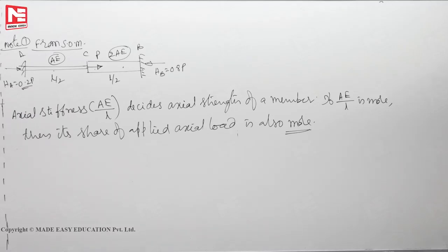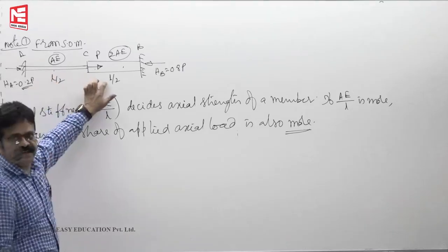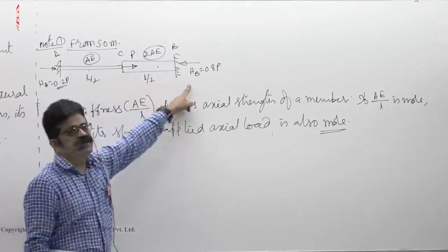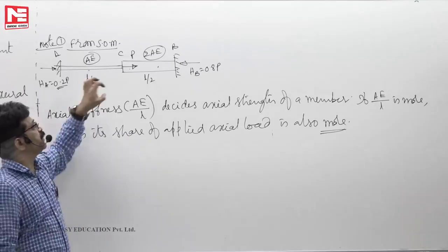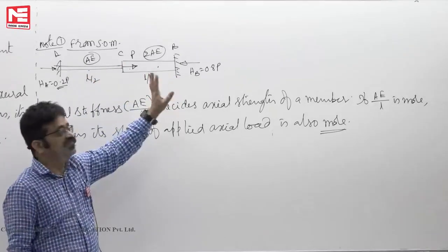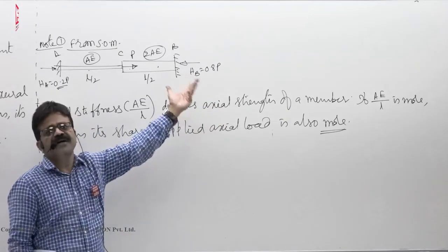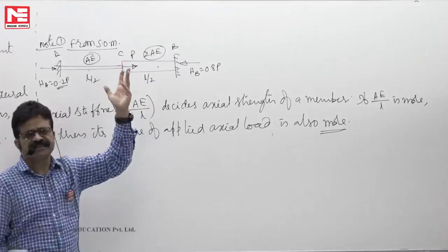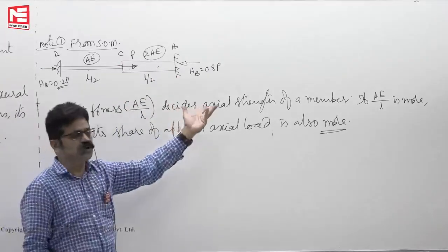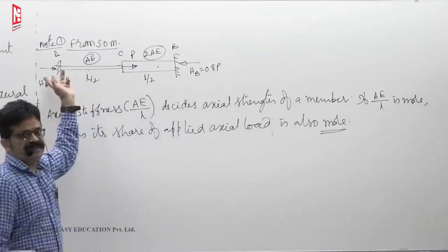If you remember the strength of materials problems, with AE and a central load applied, you might have got 0.5P, 0.5P. Then the next problem, sir might have told you, one is AE, one is 2AE. Then here the reaction is more. If not 0.8P, maybe 0.75 or 0.735, some value just slightly more than 0.5P. So 0.8 let us say, then 0.2 here.